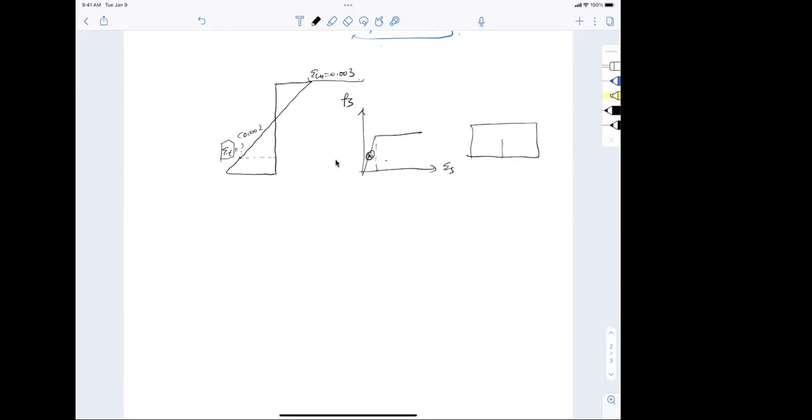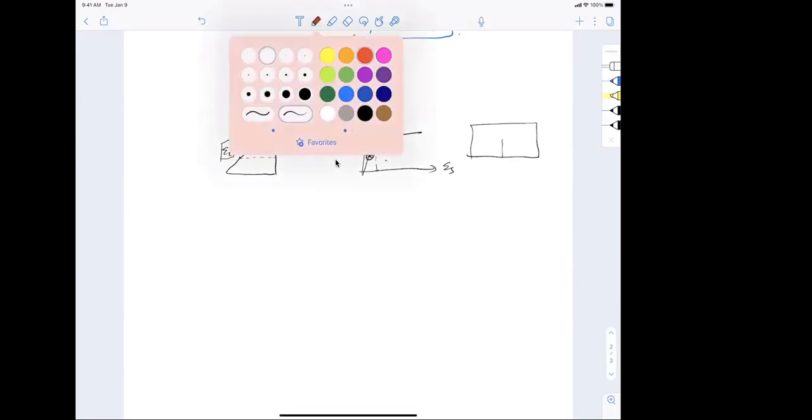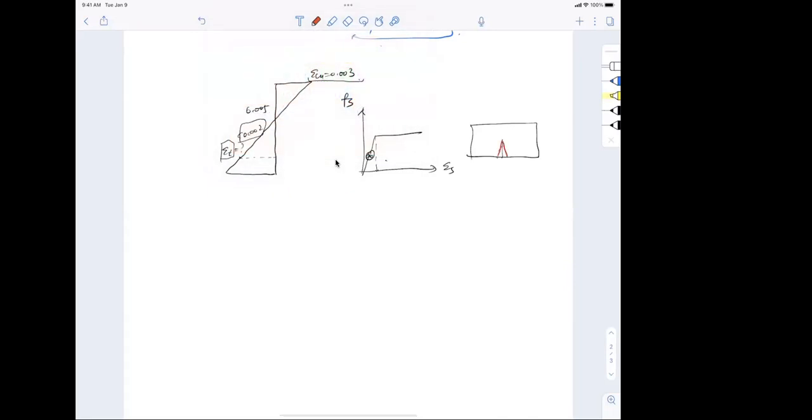If at the final failure the strain in the steel has already hit 0.05 or anything big, you will see a big crack. Oh, so we want to see a crack. Right, because you want to give a warning. If it looks ugly, it's cracked a lot, and you see the naked steel exposed like a bone, you better run. That's what we're getting at.